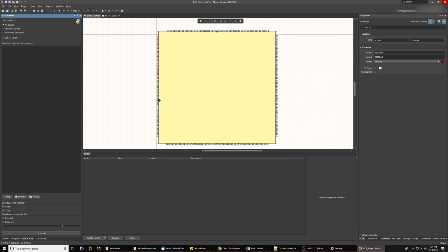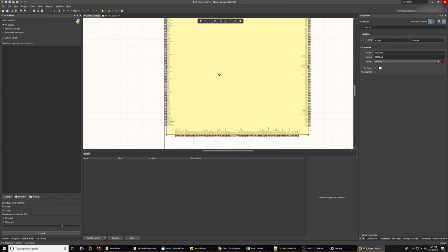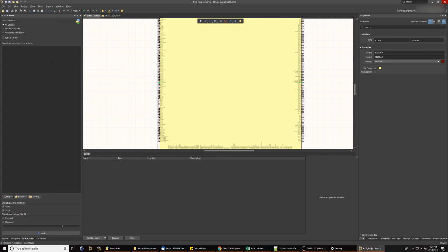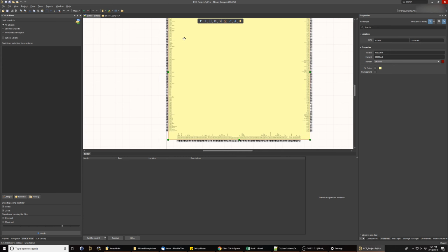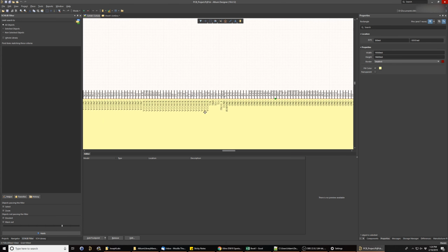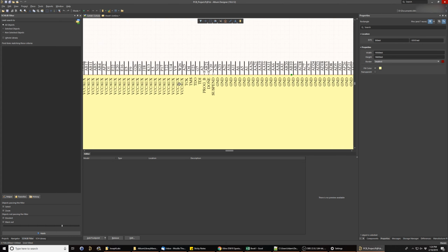I'll bet you didn't know that Altium actually has its own querying language. The language itself is described in detail on Altium's website, including everything it can do, but I'm going to specifically use the isPin and location XY queries to intelligently select pins along each side of the schematic symbol and split it into 4 different manageable subparts. To start using the query language in the schematic symbol editor,